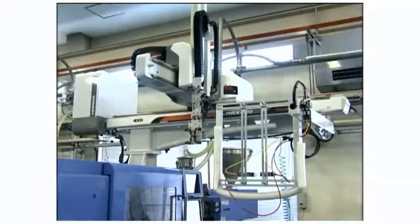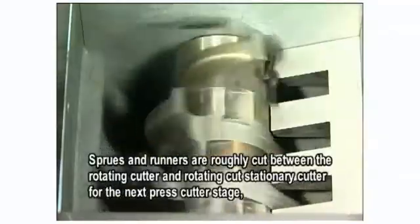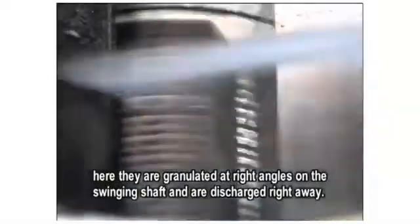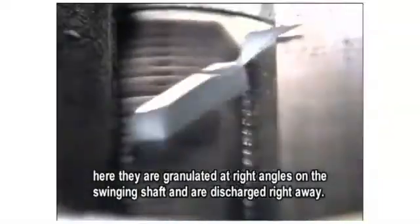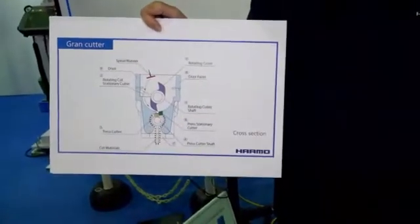The importance of this is that the runner and cutter are not touching each other many times, which means it doesn't produce powder that much. Moreover, the size of press cutter chip is decided, so the runner that passes through press cutter is basically equal sized. Of course, the quality is different depending on material size, shape, grade, and temperature, and so on. So we have press cutter demo unit.